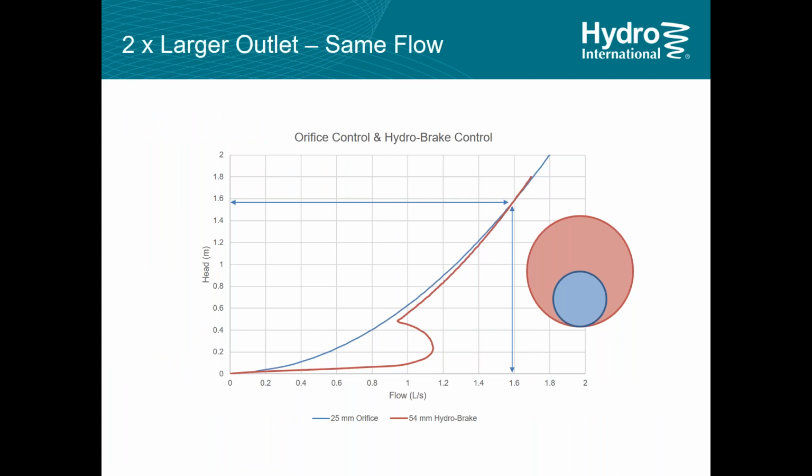Another way of using a valve is to improve the outlet condition and robustness of a design. This is getting pretty common now. I get many questions about how to get an orifice control up to a minimum size. Typically, we're seeing stricter and stricter release conditions where you've got to get back to pre-development or even pre-settlement release rates. And to do that on a small site often means a very small orifice control, usually less than 1 inch,